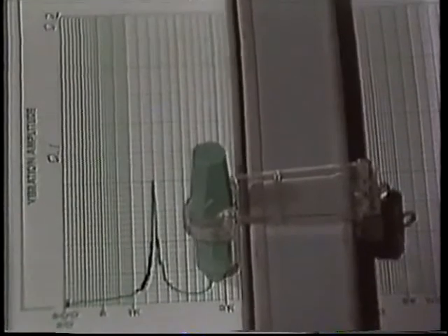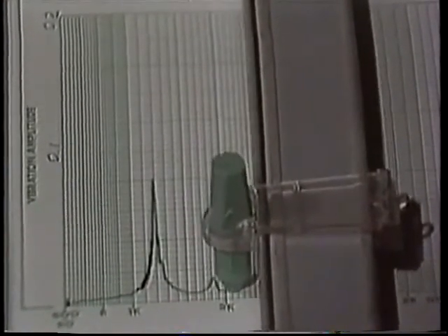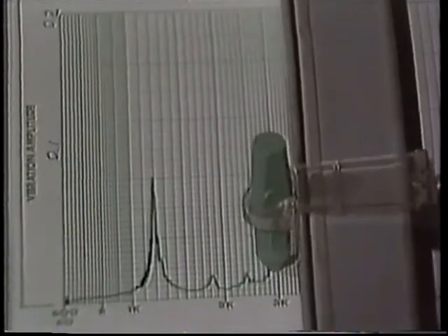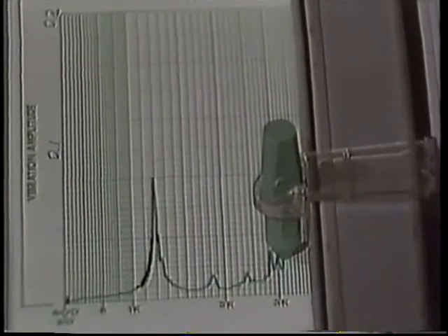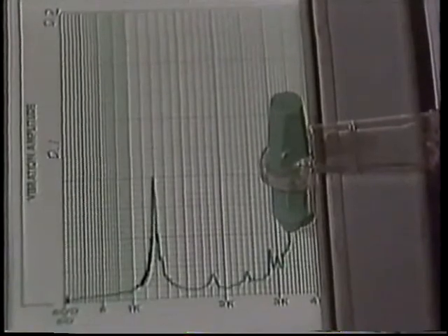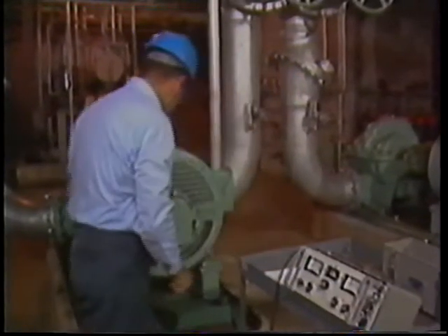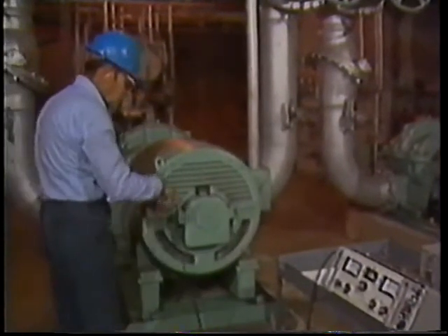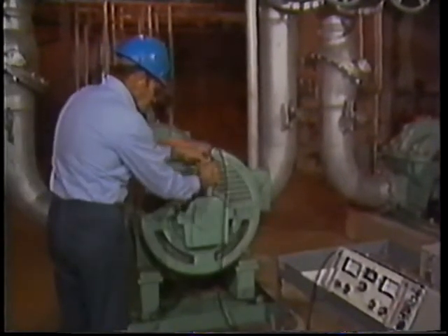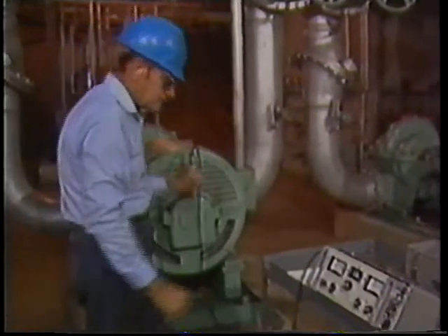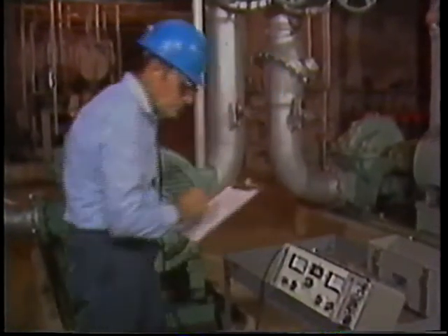Many vibration analyzers record amplitude and frequency in the form of a vibration signature. A vibration signature gives you a visual picture of vibration amplitudes at particular frequencies. As you know, when it's possible, readings are taken from three directions. You can compare the vibration amplitude on the horizontal, vertical, and axial signatures. This will help in determining the condition of your machinery.